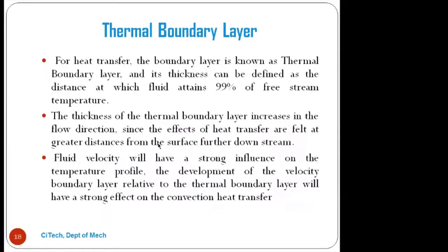The thickness of the thermal boundary layer increases in the flow direction since the effects of heat transfer are felt at a greater distance from the surface further downstream. The fluid velocity will have a strong influence on the temperature profile, as I discussed in the previous slide. In forced convection, the heat transfer rate will be much higher.